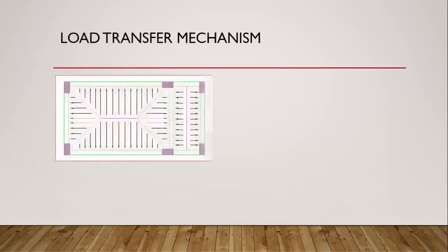Now, I will show you in the photograph how the load transfers from slab to beam, beam to column and column to foundation. Here you can see load transfer mechanism, and here is the plan view of a simple structure which consists of two slabs. One is two-way slab and one is one-way slab. From two-way slab, the load gets transferred in the trapezoidal and triangular manner to the adjacent beams, and in one-way slab, the load transfers to two opposite beams because in one-way slab, the spanning direction is only one way.